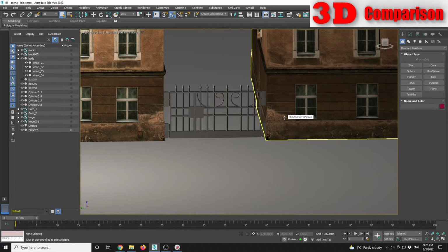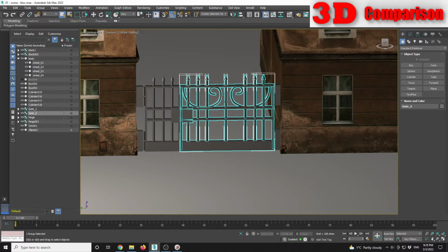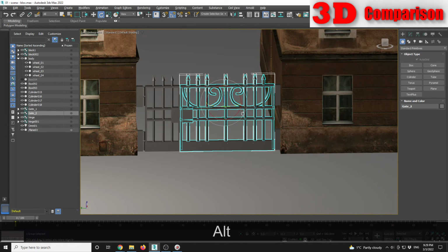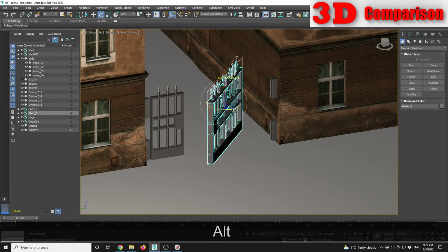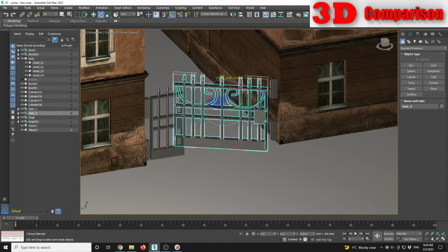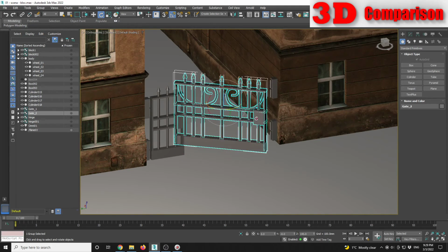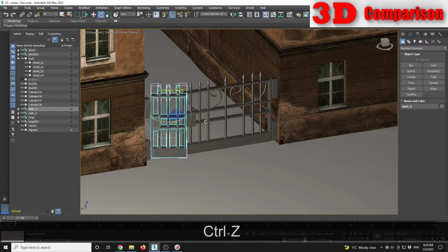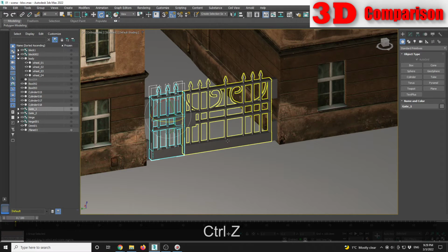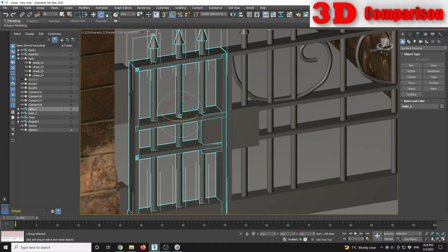And now to define the animation, we just need to adjust the pivot points of the door. So by default, if I select, let's say maybe the large door, and go to rotate, I will see that my gate will rotate like this from the middle. The same with the smaller one. So we need to adjust the pivot point. That means we're gonna need to have it translated along the axis of the cylinders of the hinge.